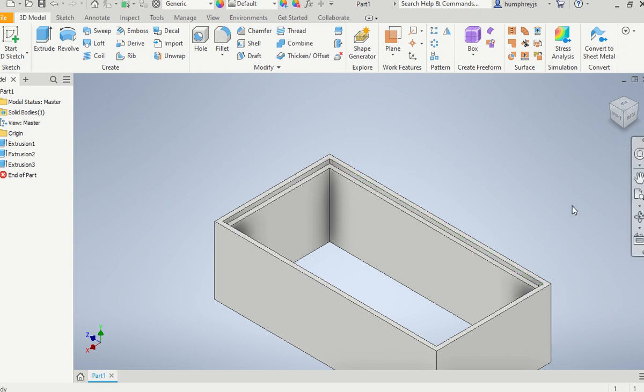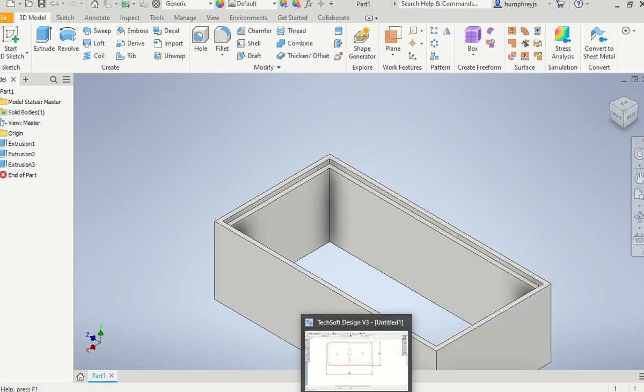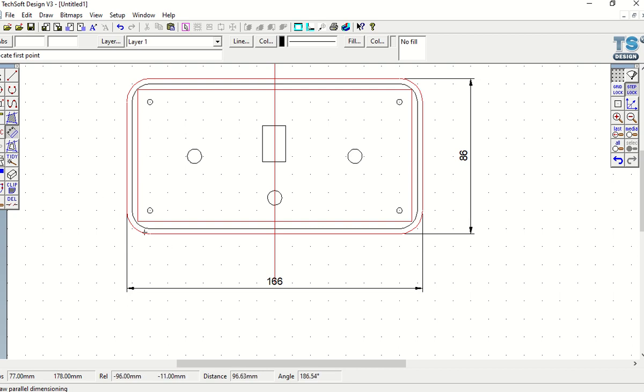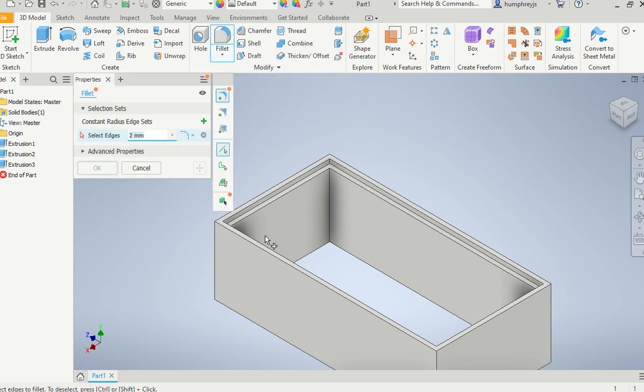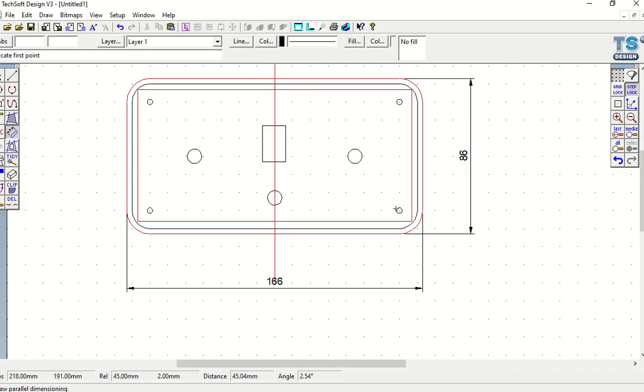Now, it's all well and good, isn't it? But I've got these sharp corners, and if you look at the control panel, it's got all these rounded corners on the outside, and this outside of the control panel, but also the outside of the 3D printing. So back to this, and we can use this tool, which is the fillet tool. Now, fillet tool takes a little while to actually load up. If we have, from the middle here, we have 10 millimeters to here, don't we? And so we have an extra 3. So from the middle, it is a 13 millimeter radius that created the curve on the edge of that box. Okay, equally well, it's a 10 millimeter one there.